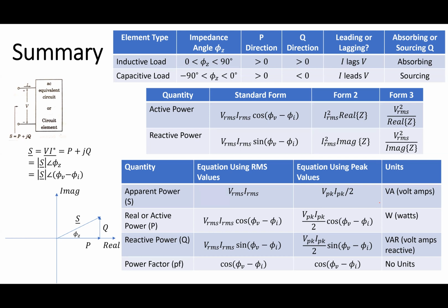If it was a capacitor, it would be purely negative 90. So when I say inductive load or capacitive load, I mean there's some R plus L, and if it's capacitive, there's always some R plus C. There's no value of R that could ever push my real part negative. That's why I can't ever be in the second or third quadrant. Let's not think too hard about that part.